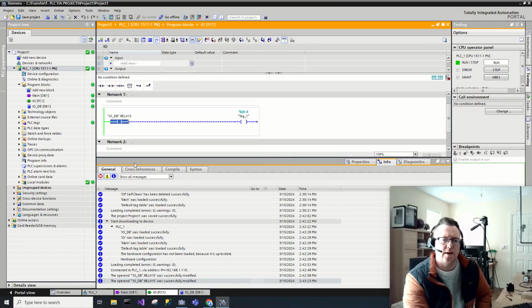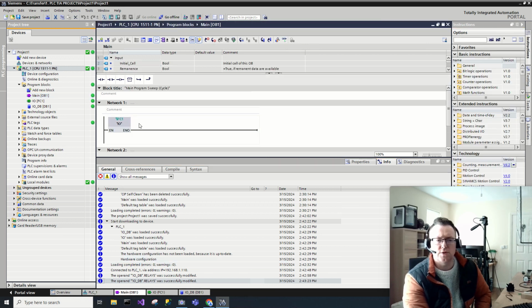So to give a recap, what I did there was I created the function. I created the data block, which is basically where global variables are held. And I did a very simple action inside this particular function. And the main program was always calling the actual function as well. So it gives the initial steps on program structure, and also some inputs and outputs that can be seen in real time. In the next video, I will focus on digital inputs using a proximity sensor. Thank you very much.